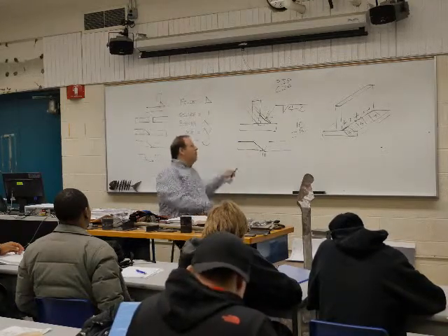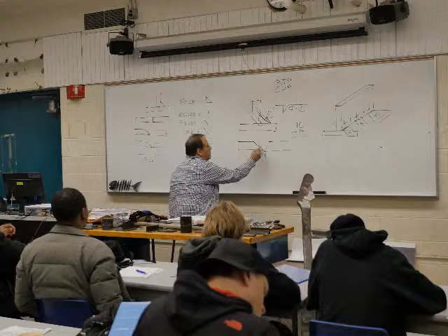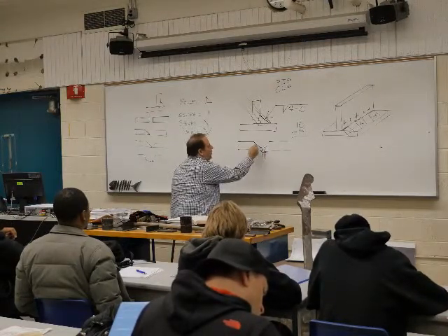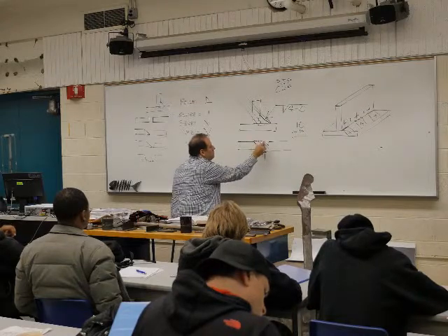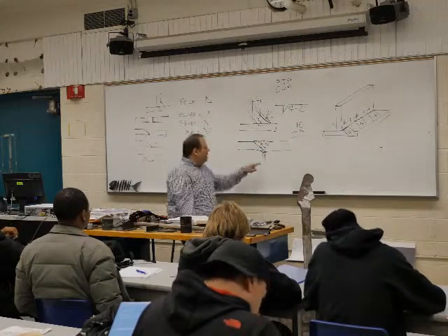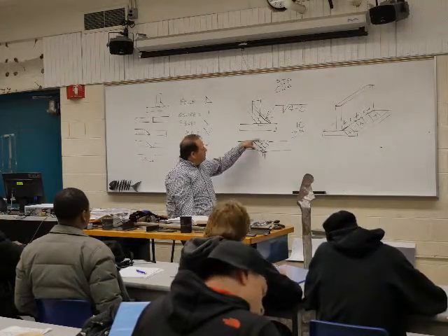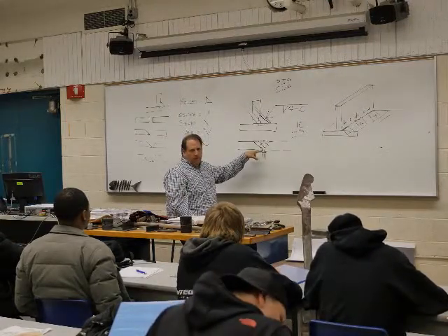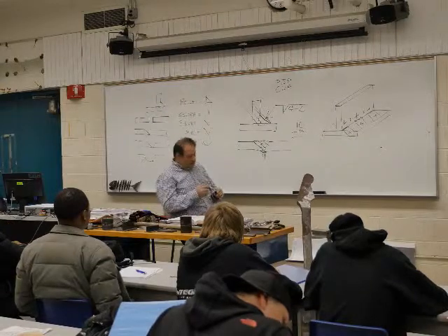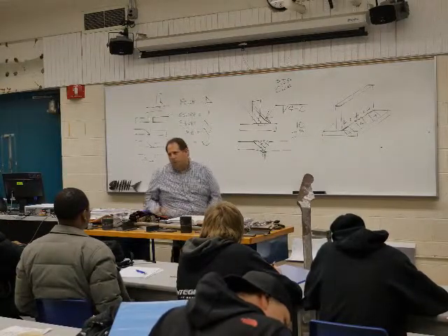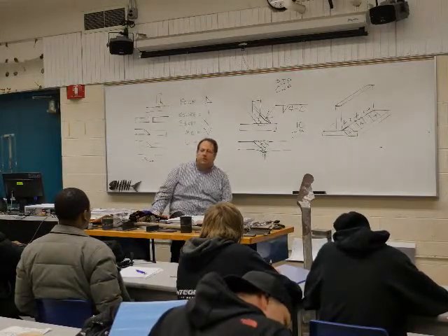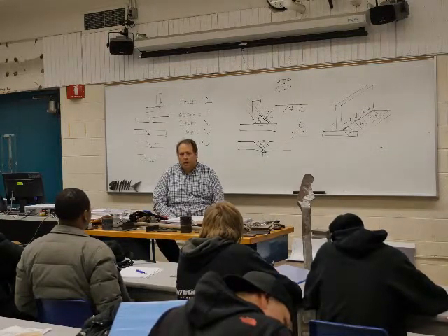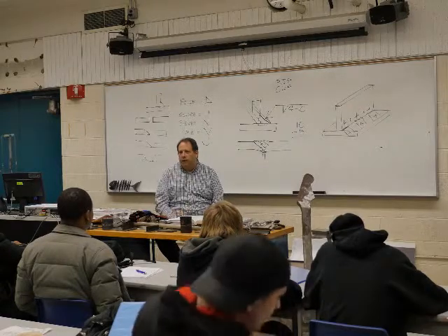Meaning that if we're going to weld this up, your first pass may be right here, and it's going to come out here, and then boom, boom, boom, and you got the weld, and it's complete, 100% from here to here. If we butt those up, you might not get that all the way through, but it may be calling for a partial joint penetration anyway. Maybe they don't want it to have complete joint penetration. There's differences, and it can be called for like that.